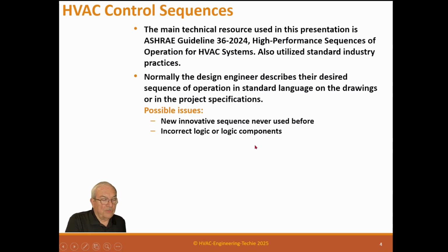Unfortunately, being a programmer is a little bit different. They don't actually write in the English language, they write in the language of special syntaxes, and the engineers have probably never been through that, so they don't understand those sequences, and they forget a lot of things. The sequence they write is in plain English. Say, I want this thing to maintain this temperature, but the control programmer has to do a lot of other things that you haven't thought about. He has to have entrance conditions, he has to have exit conditions, he needs to have timers, all kinds of reset timers, and those are things the engineer never thinks about, and it can lead to problems.